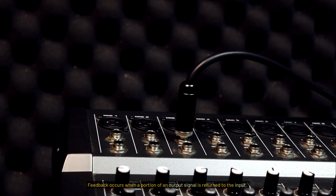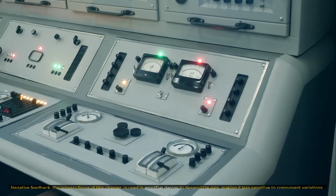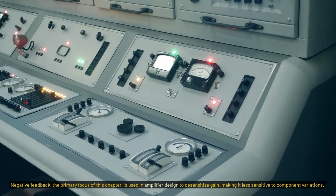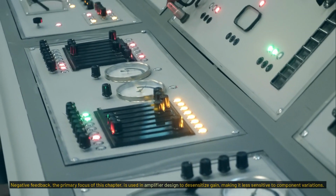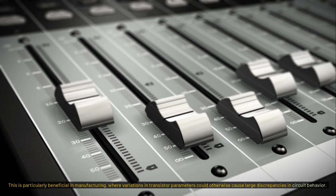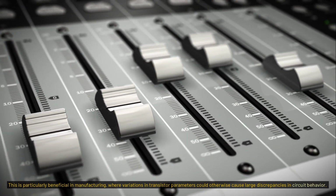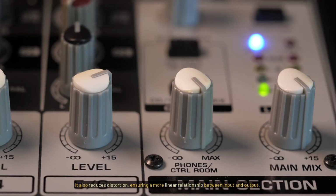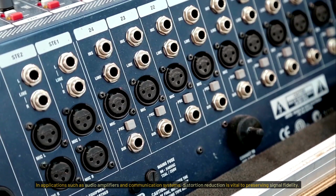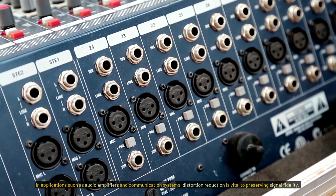Feedback occurs when a portion of an output signal is returned to the input. It can be either positive or negative. Negative feedback, the primary focus of this chapter, is used in amplifier design to desensitize gain, making it less sensitive to component variations. This is particularly beneficial in manufacturing, where variations in transistor parameters could otherwise cause large discrepancies in circuit behavior. It also reduces distortion, ensuring a more linear relationship between input and output. In applications such as audio amplifiers and communication systems, distortion reduction is vital to preserving signal fidelity.